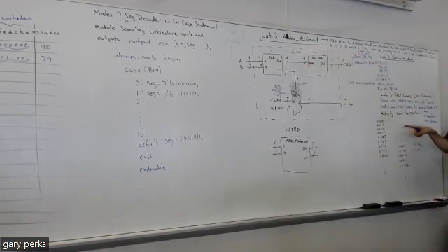And then look for patterns. Look at every even number and look at every odd number, and see if you can see a way that you can easily distinguish between the two by looking at a bit or bits. And then do the same thing for numbers that are divisible by 4. Look at 4, look at 8, look at 12, and so on, and see if you can see a pattern. Okay, and that should help you come up with the diagram that you need. Can we consider 0 divisible by 4? I wouldn't, but I would consider 0 to be even.